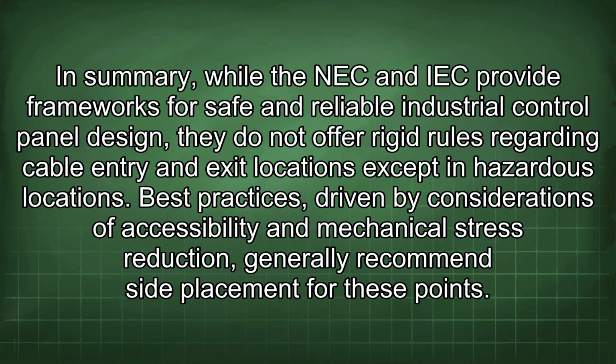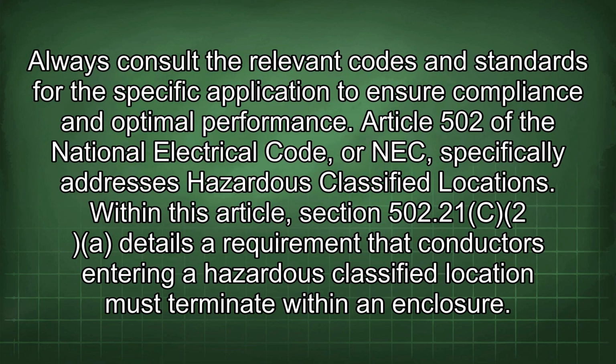In summary, while the NEC and IEC provide frameworks for safe and reliable industrial control panel design, they do not offer rigid rules regarding cable entry and exit locations except in hazardous locations. Best practices, driven by considerations of accessibility and mechanical stress reduction, generally recommend side placement for these points. Always consult the relevant codes and standards for the specific application to ensure compliance and optimal performance.